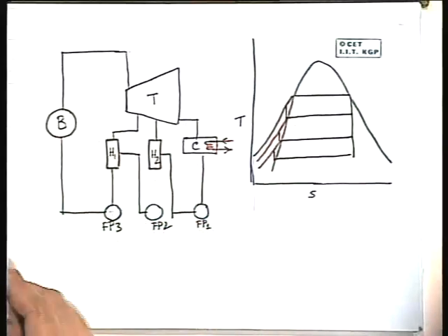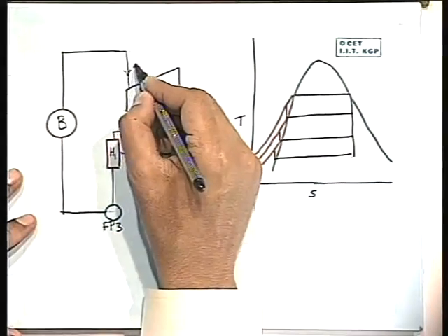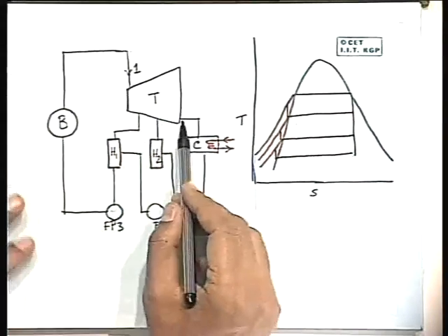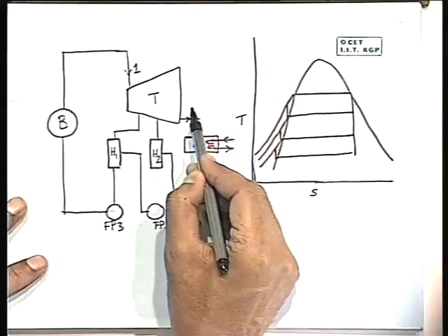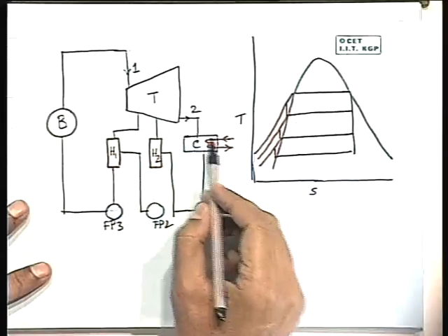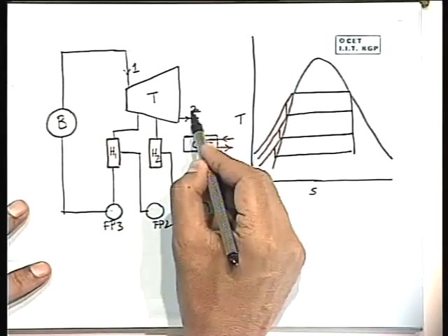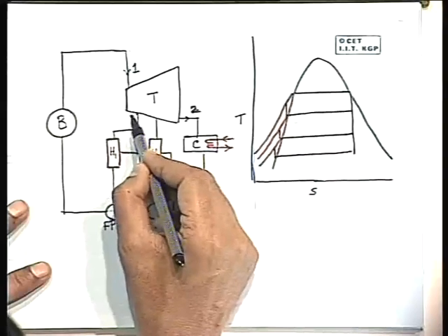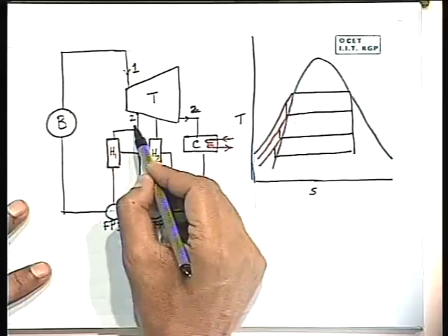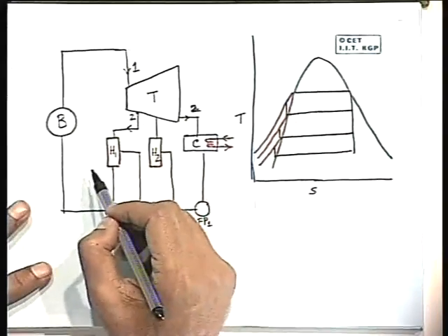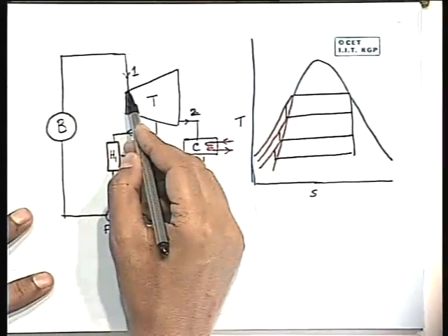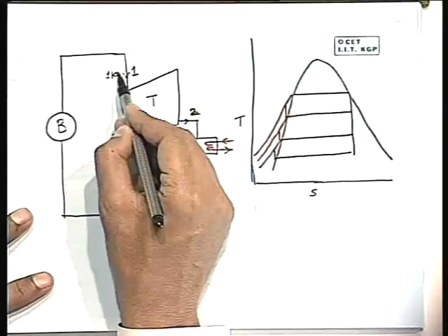Let us consider this boiler here, and the steam enters at some pressure and temperature, the boiler pressure and temperature, at this point 1, and this steam expands up to the condenser pressure. Let me just draw this figure like this. Let us consider this point 2, that means steam after expanding to a pressure corresponding to 2, some amount of steam is bled for the regenerative feed heating. Let us consider the analysis for 1 kg of flow at the inlet to the turbine. Let the flow rate here be 1 kg at 1.